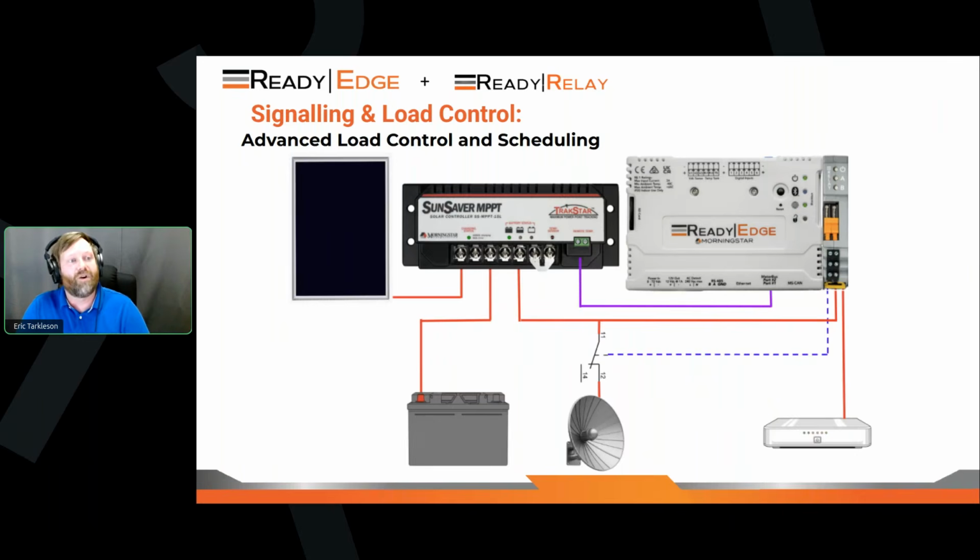And then, with modems, it's 2026, but the best way to fix most computing problems is to reset it, turn it off, turn it back on. So in order to stop our modems from hiccuping after being on for weeks and weeks or months at a time, we're going to set a schedule to turn off the modem for 1 minute every Sunday and then turn it back on, effectively resetting and rebooting the device. And that gives us a way to make sure that we don't run into communications hiccups or devices freezing. And there's a lot of different options we can do with load control, but this is just an example.